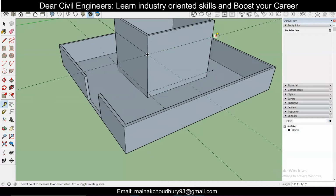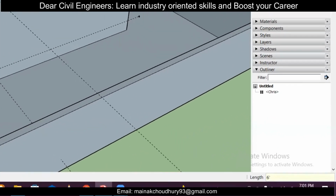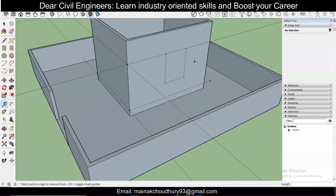So you can measure this. The length will appear on the screen. This is 14 feet. Let's go 6 feet for the windows here. 6 feet, enter. Once you have this 6 feet here, you can go 4 feet 6 inches. This is the window height, and 2 feet 6 inches is the sill level, the window bottom level. And let's provide a window of 3 feet 6 inches here, and then just close it like this. So you can do it like this.